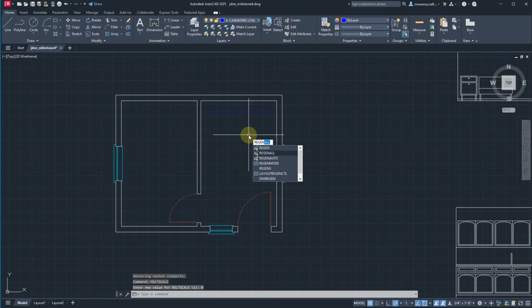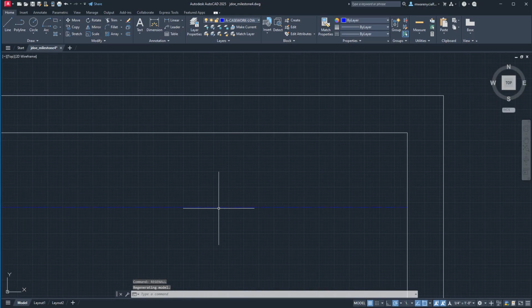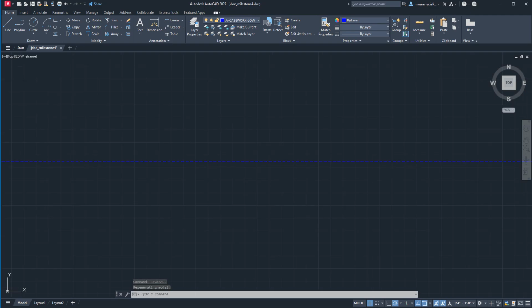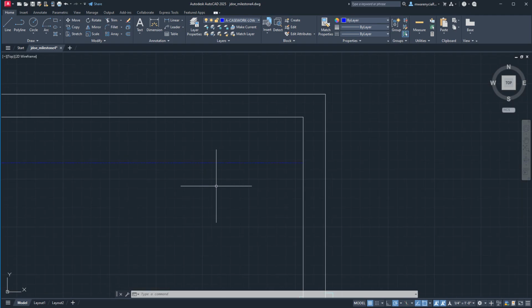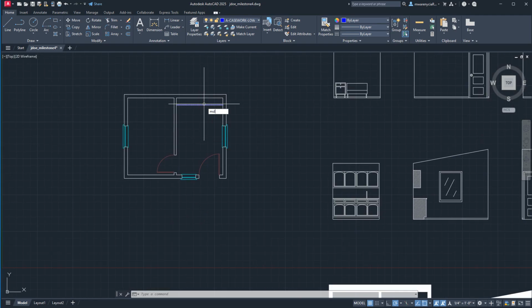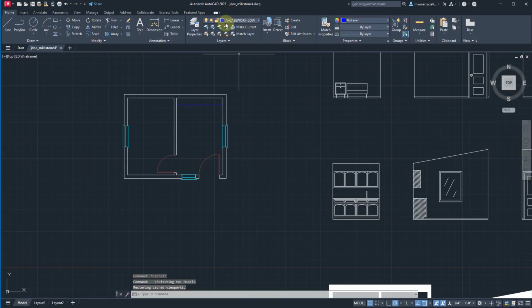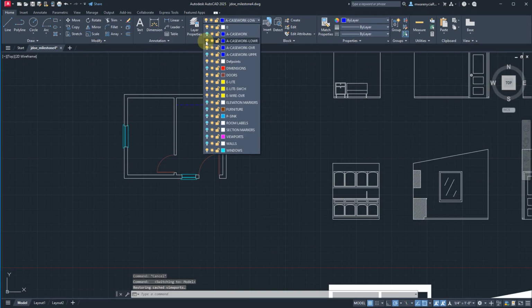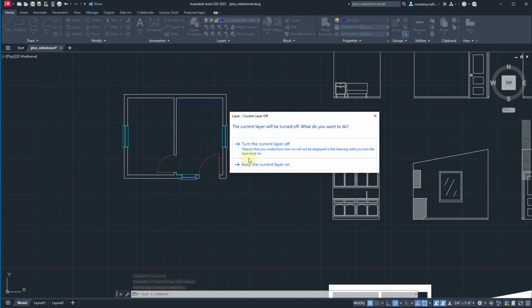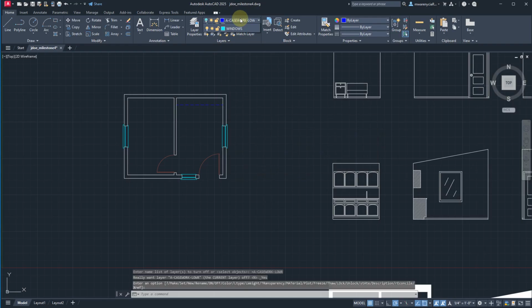So if we do set that to 0 and then regen all, again, you can see here that it's not scaled at all either, so it's very tiny. So we'll run MSLT scale, set it back to 1, regen all, and there we have those showing up. Just double check that they're showing up correctly. Okay, so generally you don't want to mess with the others. You just want to deal with the LT scale, and that's it.